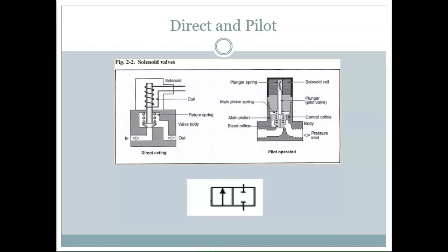So what you have are pressure relief valves. What those are looking for is for your system pressure to become too much. And what it will do then is actuate this over so that it drains any excessive pressure off to the tank, or vent it if it's pneumatic.